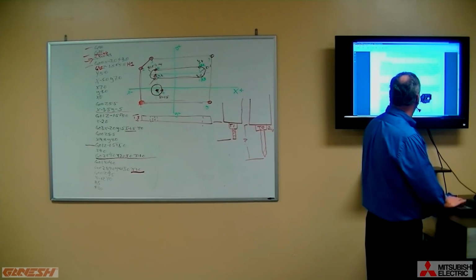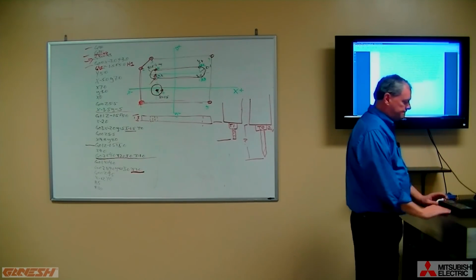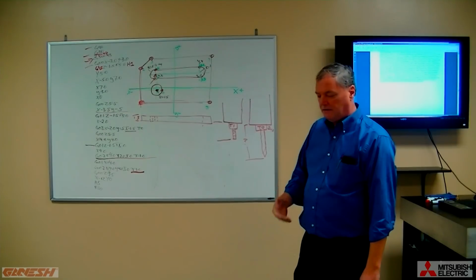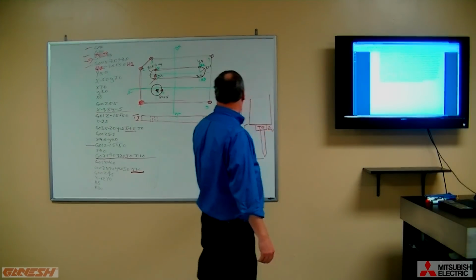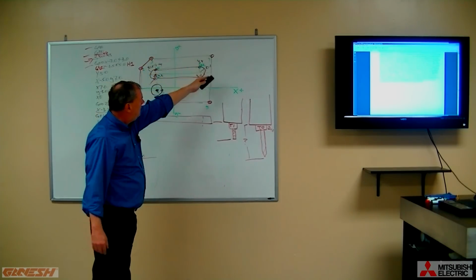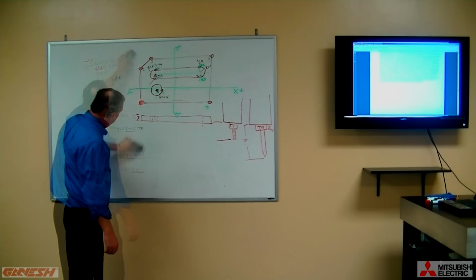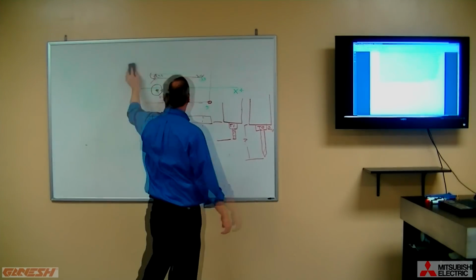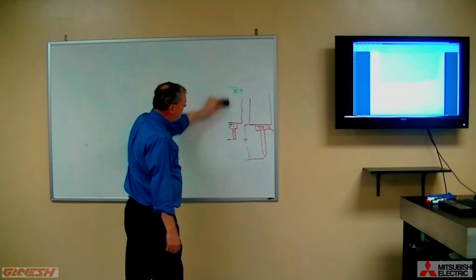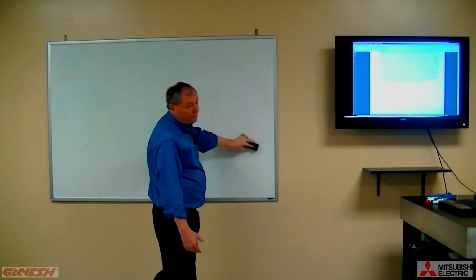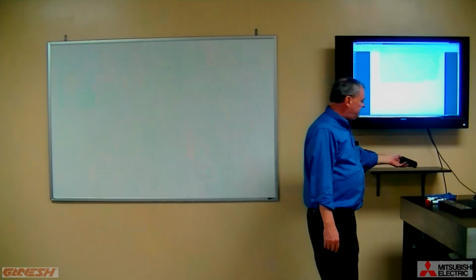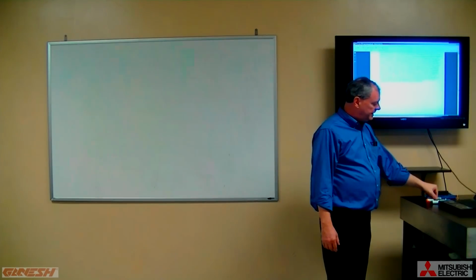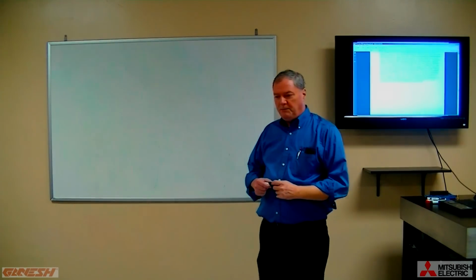At this point, I would like to talk about drilling and what we call fixed cycles. Up till now, we've just been essentially moving an end mill around different parts of a component that we're machining. In reality, most parts that we make will have a series of profiles that need cutting, and they'll also need what we call single point machining operations. A single point machining operation would be something like a hole.